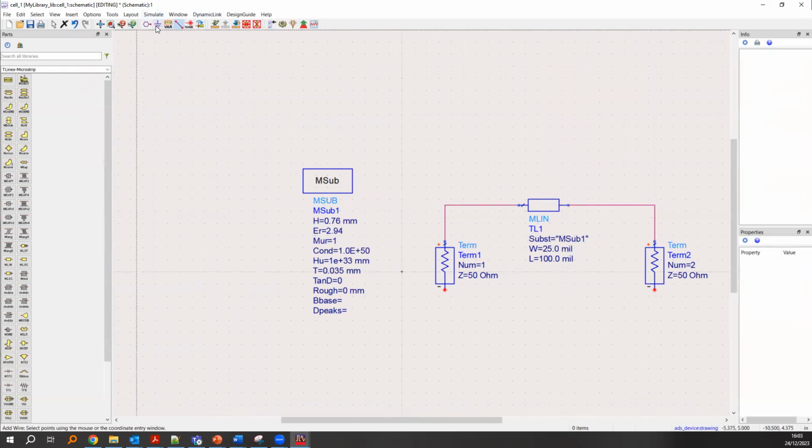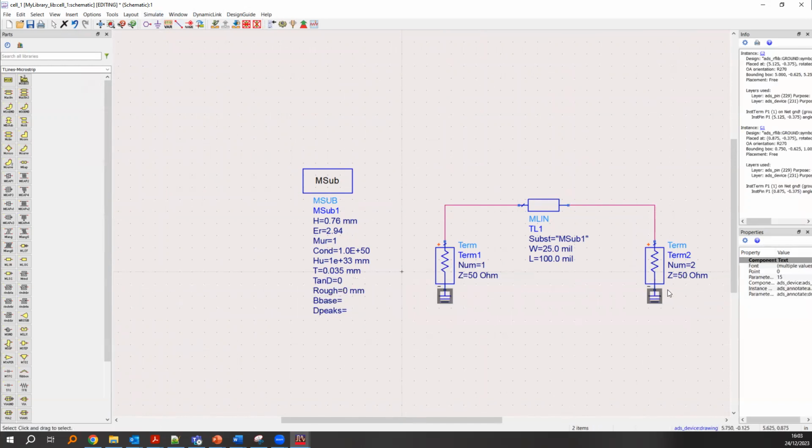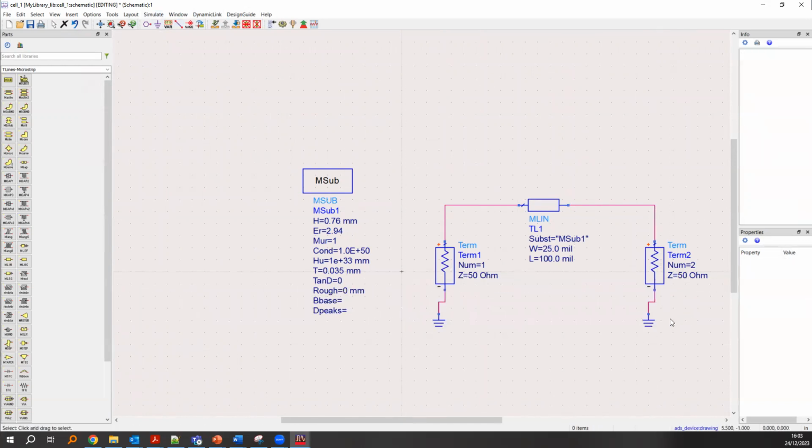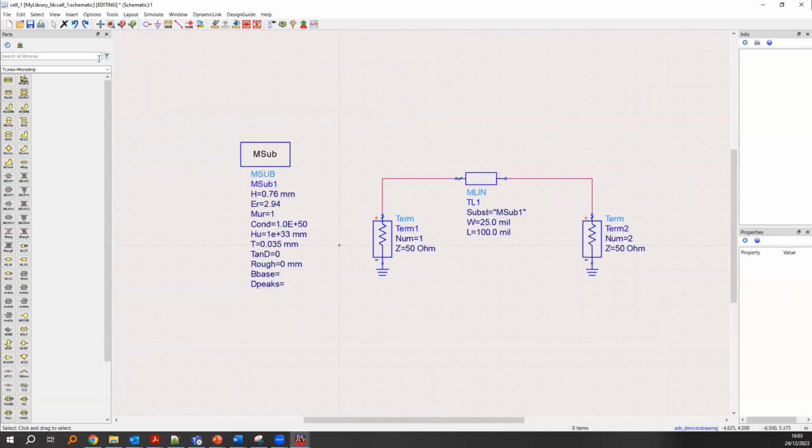And because the circuit currently lacks the reference point, we can add the ground to both points. And an alternative approach to doing this will be to just simply add a line and use one ground, which makes it easier for you to keep track of the grounds. But in ADS and in the same schematic, all grounds are referenced to the same point. So whenever you're adding this short circuit symbol, you're basically shorting all the grounds to one point. Now we have the schematic.